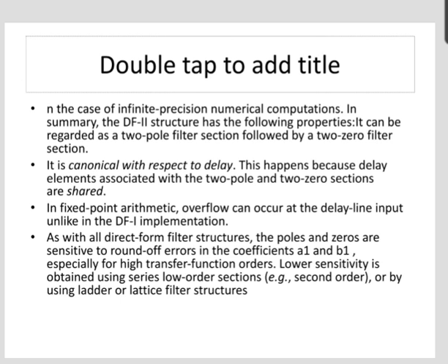In other words, it is common for the feedback portion of the DF2 IIR filter to provide a large signal boost, which is then compensated by attenuation in the feed forward portion. As a result, if the input dynamic range is to remain unrestricted, the two delay elements may need to be implemented with high order guard bits to accommodate an extended dynamic range.